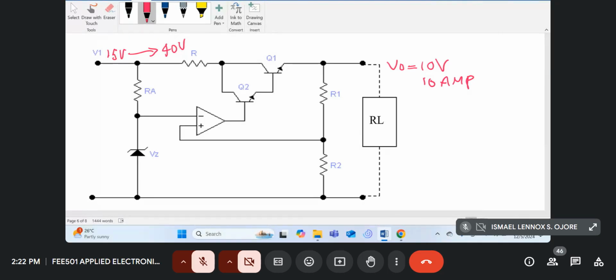If you look at the voltage side of things, first of all, remember this op-amp is normally connected to the power supply. And we saw for the National Semiconductor, you can connect maybe minus V, the maximum voltage across the op-amp was positive 18 and minus 18.